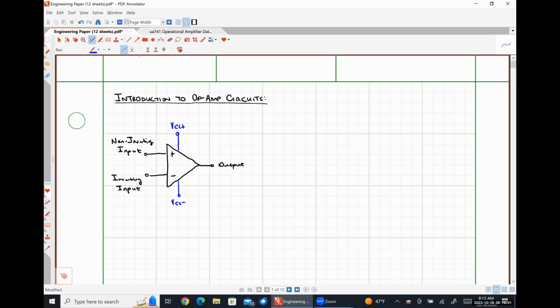So while these pins won't influence our circuit analysis literally at all, they are critically important because an operational amplifier is our first component that is an active component, meaning that it requires external power for it to work. A resistor exhibits resistance regardless whether or not it's plugged into a circuit.